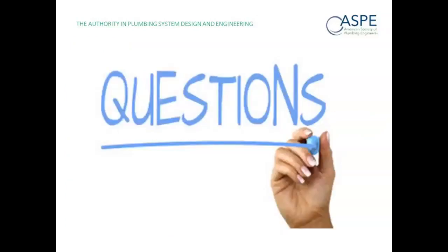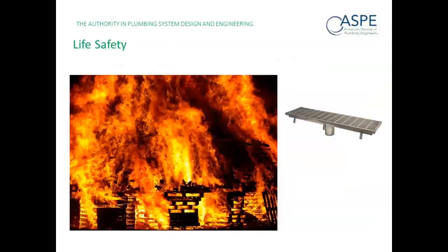I had another thing on there. What I was talking about, and you see the threshold drain on the side. This is really out of the California Building Code, and that has to do with the drainage of water from the threshold, so you don't get water into the elevator hoistways, because those hoistways are critical to firefighting operations.